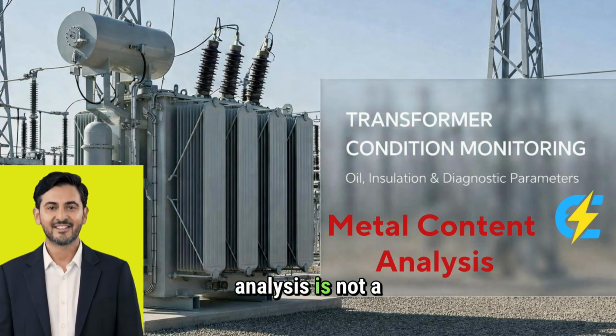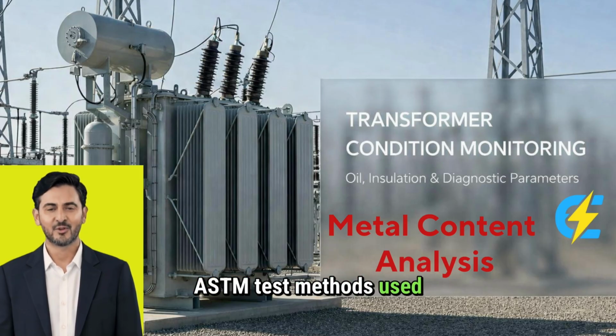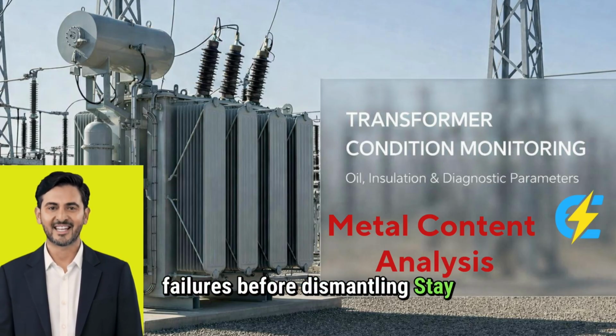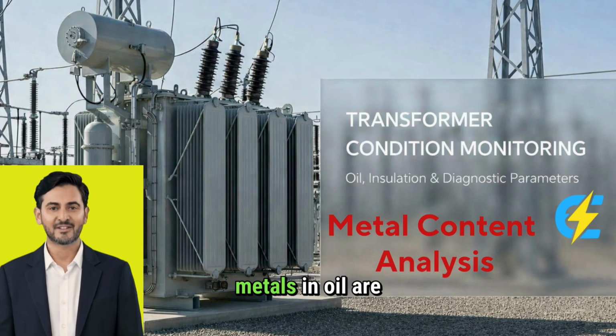Why metal analysis is not a routine test. Which metals indicate which internal component. IEC and ASTM test methods used. Why standards do not give fixed alarm limits. How trend and metal pattern reveals internal damage. And how metal analysis confirms failures before dismantling. Stay till the end, because metals in oil are physical proof, not assumptions.